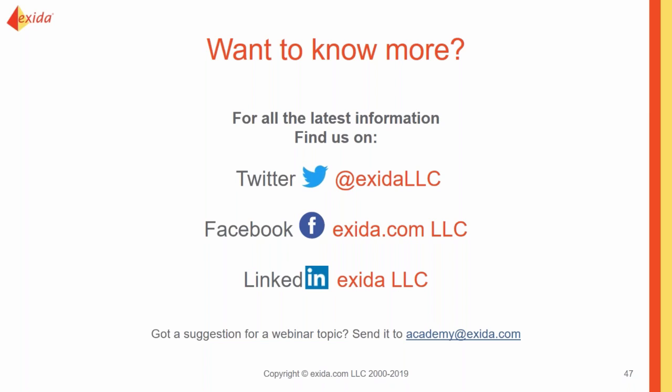And then last question we have, I think. So if you say, for example, you have a facility with several SIL 1 CIFs, say around 60 are required, only two SIL 2 CIFs, and maybe a SIL 3. Is a SIL 3 capable CIF required, or is a SIL 2 capable CIF sufficient?